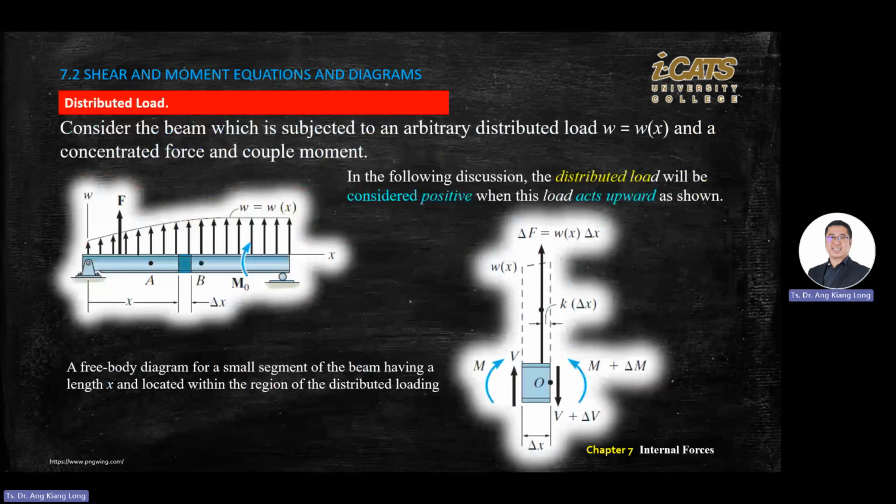Okay, notation of the way you cut. On the left always go up, on the right always go down, and then moment on the left will be clockwise, moment on the right will be anti-clockwise.